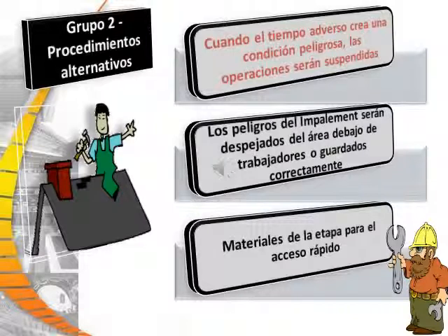When adverse weather creates hazardous conditions, operations shall be suspended. Impalement hazards shall be cleared from the area below the workers or shall be properly guarded. Again, all staged materials should be placed for quick access.